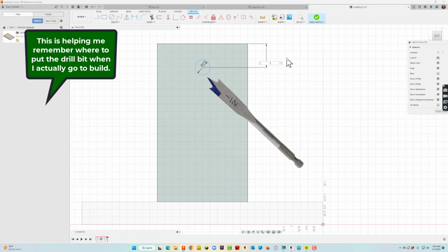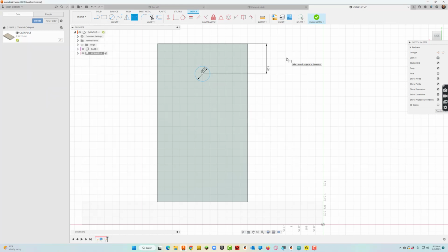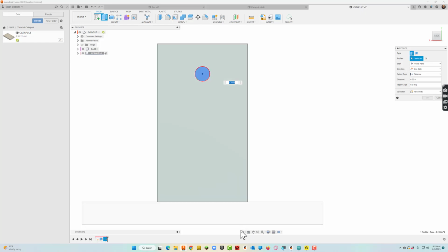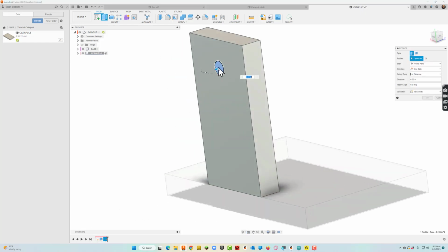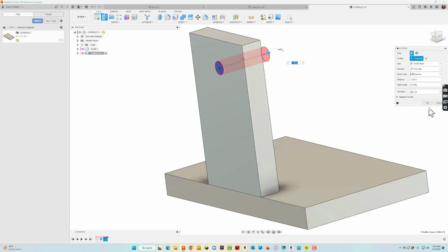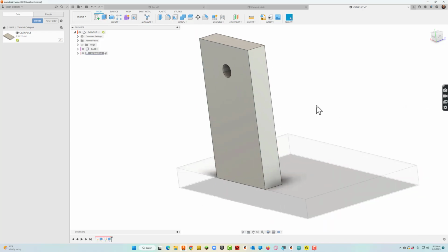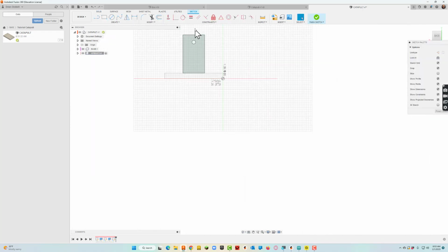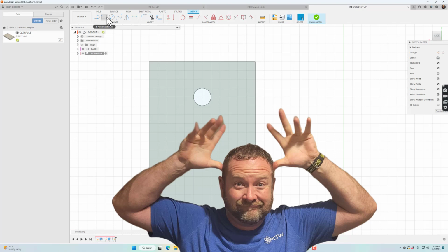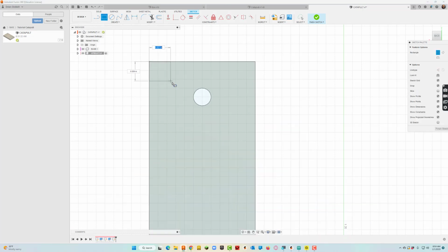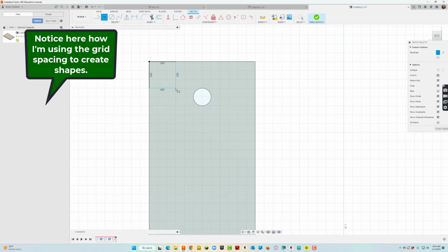Let's use some pretty numbers. So let's make that maybe a 1. From side to side, I already kind of located it with the midpoint. So it should be 1.5. And I'll go ahead and cut this thing out because it's supposed to be a hole. So there it goes. And I tell you what, while I'm here, I'm going to make a spot for this stopper to be. Remember, we have to have some sort of way to stop this thing. And I know again that it's 3/4, so I'll probably just use 3/4.